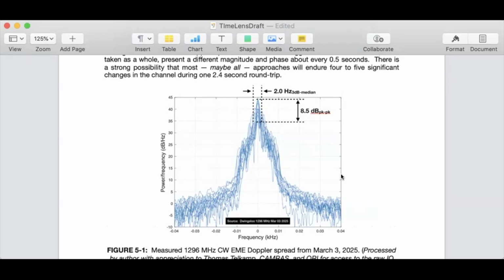Seems like the channel probably creates new realizations about every half second. Just guessing. So if you think about the up and down time to get a signal optimized for the lunar surface, it probably innovates the channel about 4 or 5 times. And for that reason, I really don't expect that the coherent stuff is going to be practical at all. Maybe, but probably not. But in order to write the theory and work it out, starting from matched filters and rakes, I decided to break it down to the very simple thing and then build it back up into the tricky thing and see where it goes.